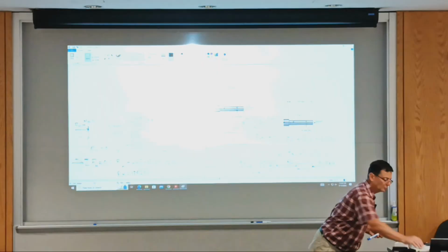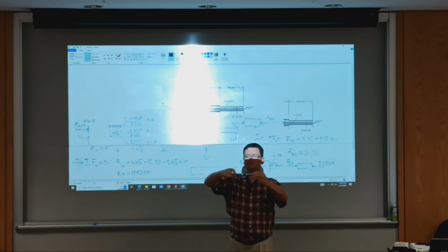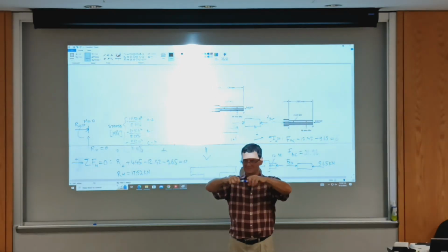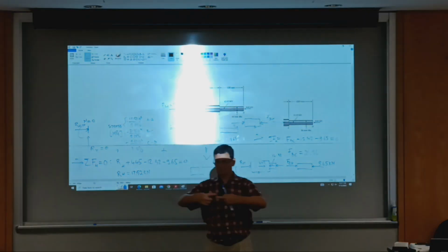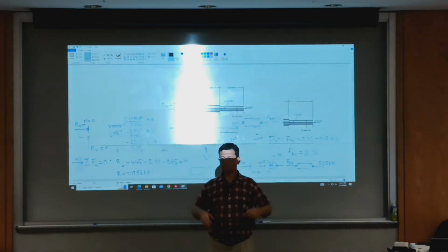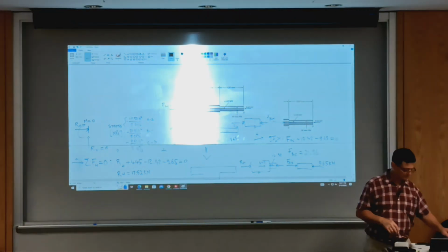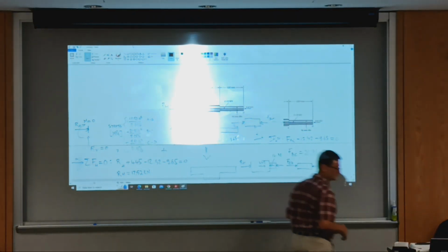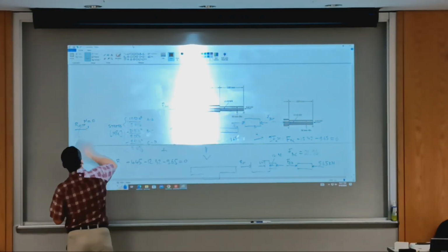So if you think of a beam that's loaded from above, the below part of the beam is in stretch, and the top part is in compression. So at least for that reason, you would say the horizontal sections of that trapezoidal frame should be in tension, but we got compression, and that didn't look right. I solved the problem before, but I went over it. So that's why I sent you the correction.